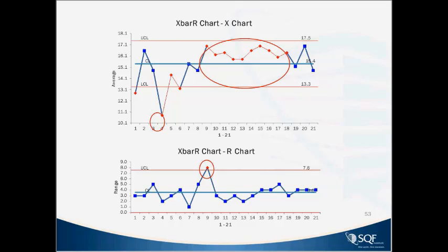Now these control limits, it's recommended that you set a frequency of looking at data and seeing, do I need to recalculate the control limits? You can set that on a monthly basis, every 2 weeks. You set the frequency, I think, based on how much change you might expect or how long you think it might be for operators to use control charts and drive variation out of the process. It may be a very long time, but at some point in time, if they're using the control charts properly, they will be driving out.